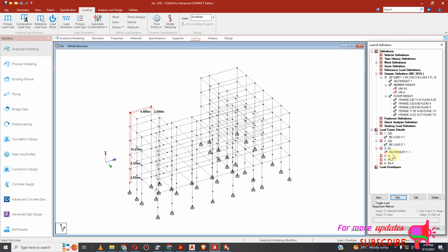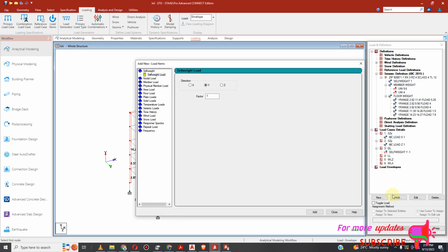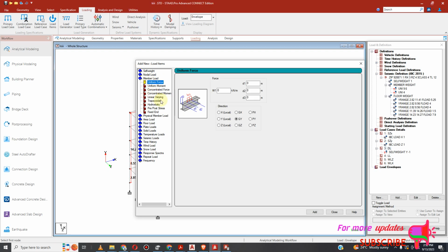So we start by dead load, and also we add again for our unit weight. Okay, so go to the member load, because we said that for walls is 9.6. That's now this time negative, don't forget that, in the global Y direction. Then for parapet is 0.4, add.